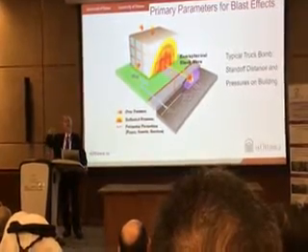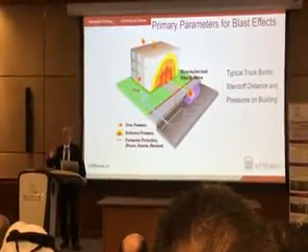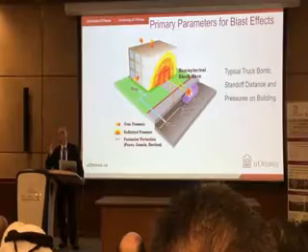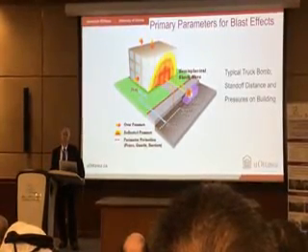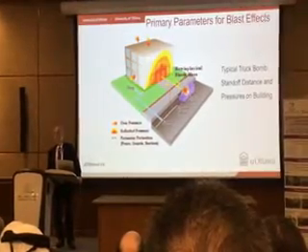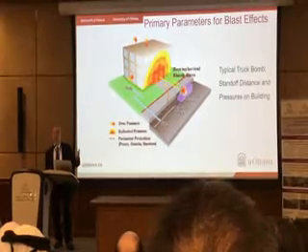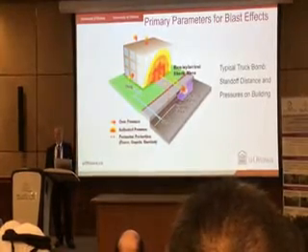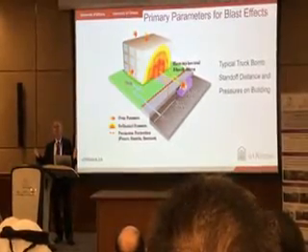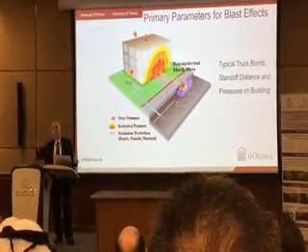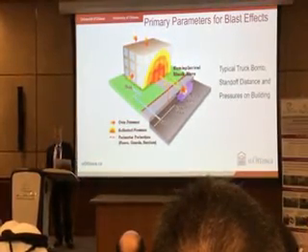But then another shock wave is coming as well. So there is turbulence in front of the building. This reflection increases the magnitude of the pressure. So we deal with reflected pressure most of the time, especially for the front facade, and not incident pressure. So we have to be familiar with these two terms. And then there will be incident pressure causing drag forces from the side walls, from the roof, and even from the back wall with some time delay.